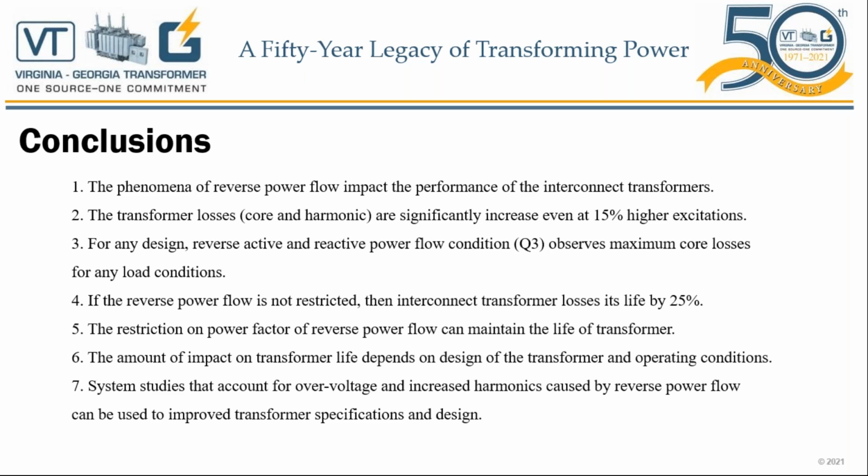And let's not forget, when we talk about increasing excitation in transformers, I'm sure most of you on this webinar know, increasing excitation means increasing sound level. The transformer has no-load noise and load noise, especially for larger transformers. But for small and medium power transformers, the main source of sound is the core. When the excitation of the core starts going beyond the design limits, as it gets towards its limits, the sound level will increase tremendously. So these are 7 of the main conclusions that I wanted to note down for our presentation today.